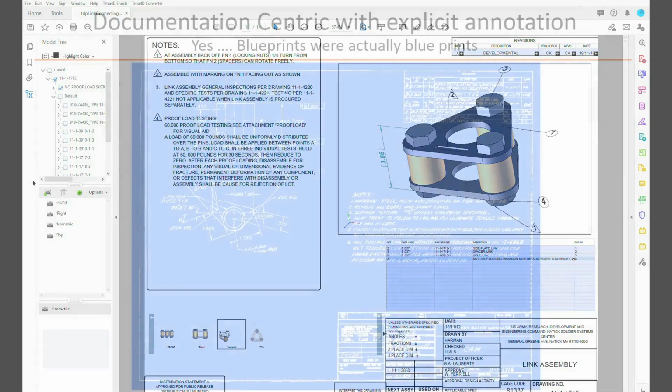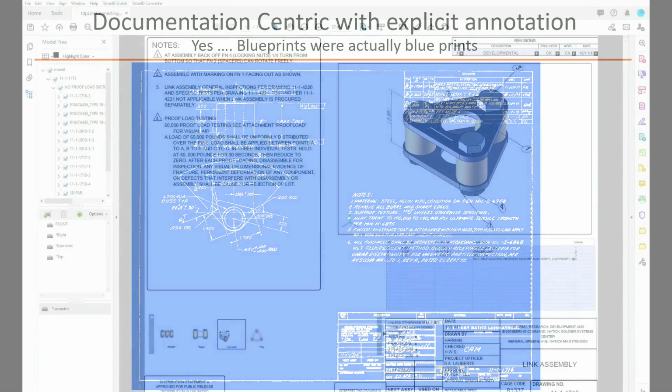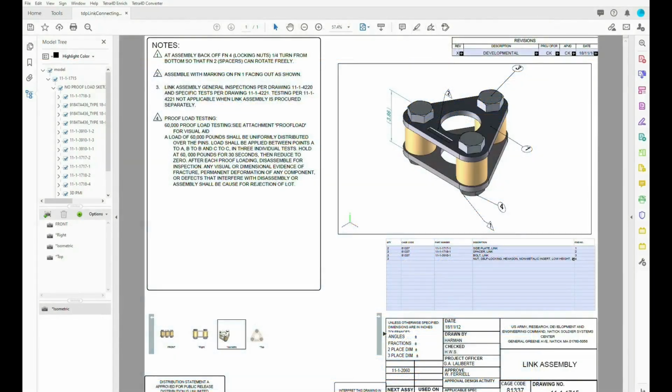We are still in an era where the predominant means of communicating product details is the engineering drawing. The contractual artifacts generated by this prototype will provide a 3D technical data package. The majority of 3D technical data packages currently in use are basically 2D drawings with an embedded 3D view and attached 3D files. The current generation of 3D technical data packages have static views in which the annotation has to be explicitly placed and will move with the geometry. This can be a very labor-intensive process and may require some relatively expensive add-on software for the authoring system.